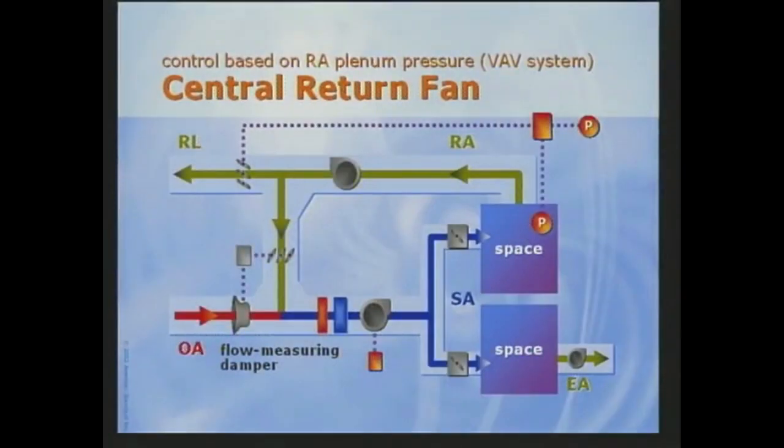If used, it's likely to result in wide fluctuations in differential airflow and building pressure. A fourth control method adds hardware to adjust return fan capacity in order to directly control building pressure. A controller modulates the relief damper to maintain the building pressure in the desired range. The return fan is then modulated to maintain a constant static pressure in the return air plenum, downstream of the fan. This method can maintain building pressure in the proper range in all operating modes.